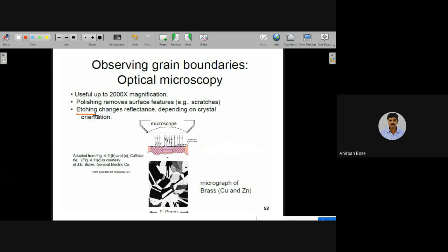Etching is a process after which, if we see the sample under a microscope, the grain boundaries can be clearly identified. So what is this etching process? It is basically a chemical, and this chemical may be an alcohol and acid solution. Different kinds of etchants are there, and they are recommended for different kinds of samples. Depending on whether it is a steel, there is some recommendation of chemical, that is, etchant. So what is done in this etching process? This chemical is given on the surface, and it will definitely try to react with the surface.